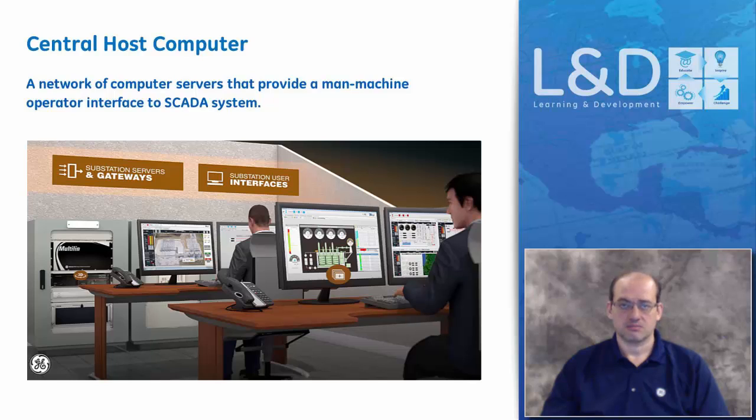The SCADA system also allows for document management and outage management. So when a utility incurs an outage for any reason at a substation, the SCADA system might have a component that will take care of answering the affected individuals and keeping them updated with hourly information about the resolution of the issue, based on the documentation released from the dispatched person or the local operator.